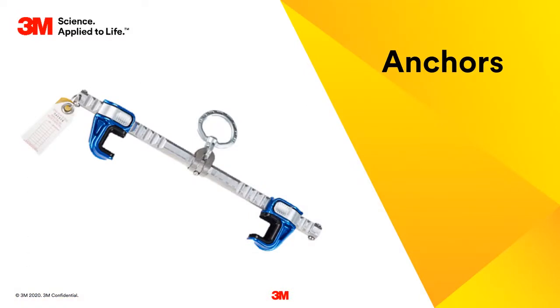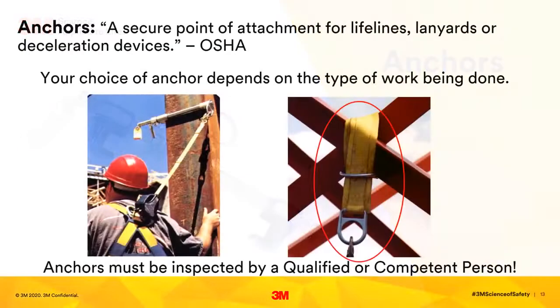Fall arrest equipment that has been exposed to a fall arrest or fails an inspection must be removed from service immediately. Some equipment, such as self-retracting devices, may be sent back to the manufacturer where they are repaired and can be put back into service. The anchor refers to the structure, wood, steel, or concrete. The anchorage connector is the adapter or the device used to attach to the structure.